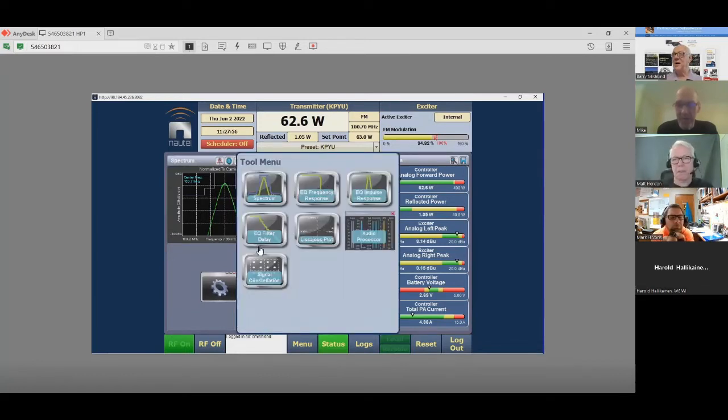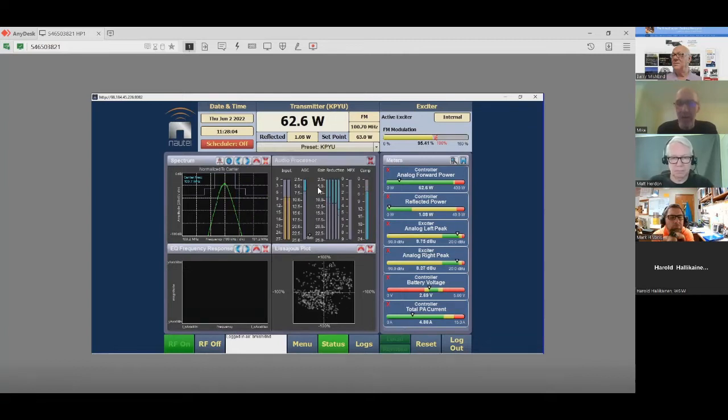Yes, it does. There is no signal constellation because constellation is a demodulated HD OFDM signal. So in the modulation that occurs in a digital system, the sidebands are quadrature phase shift keyed. They have 4 possible states once the symbol's been impressed on the carriers, they can run at 4 possible phases.